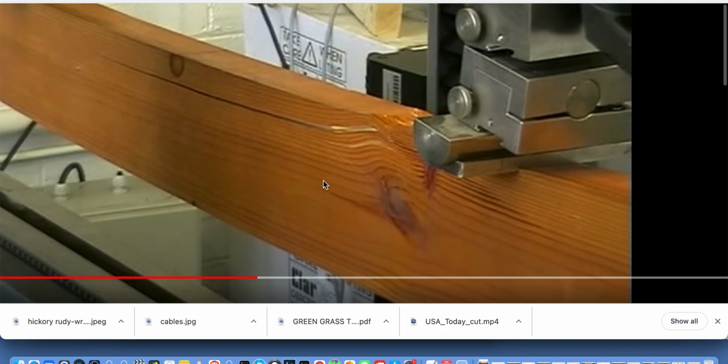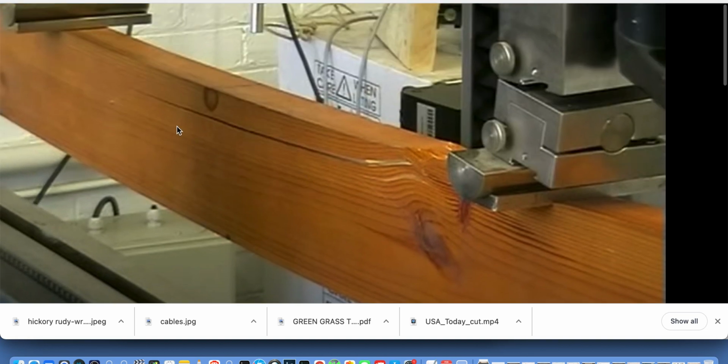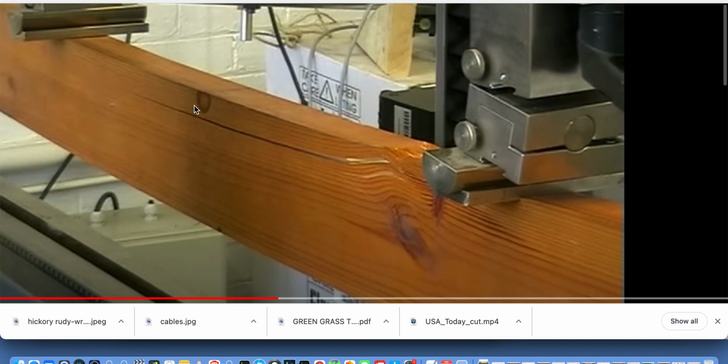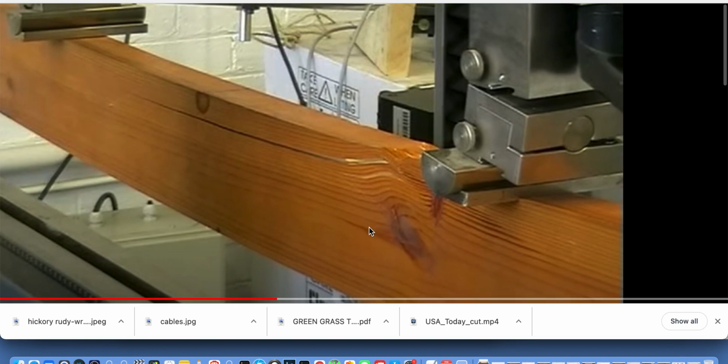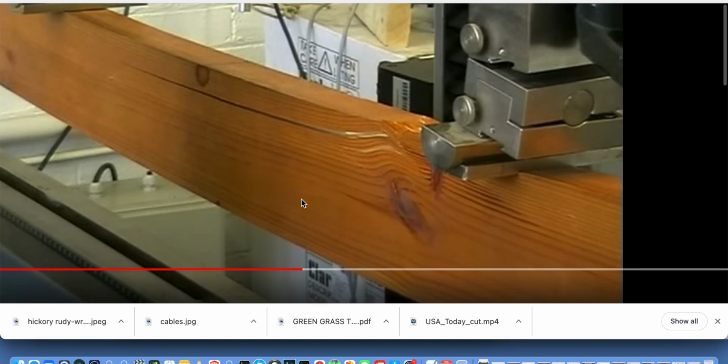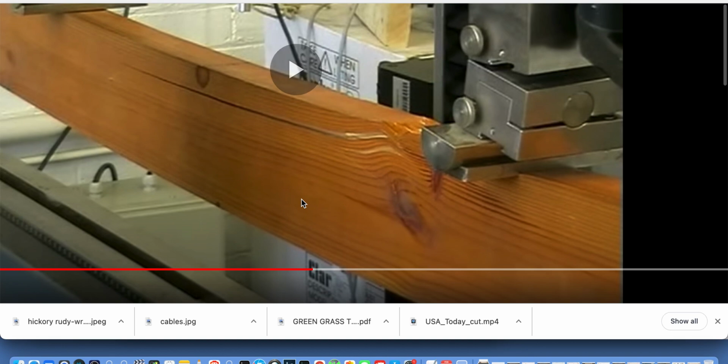So now what's flexing is the new fibers in here. Remember, the moisture content counts on this, how much it's going to stretch. So just because this is a 2x4, 2x10, whatever dimension it is, they're not all going to behave the same. This behaves differently than the others. You can't extrapolate that. Each one is what I'm driving at. Each one of these is going to behave differently depending on the knot structure. And this will prove it because this is going to fail based on the knot structure. And here she comes.